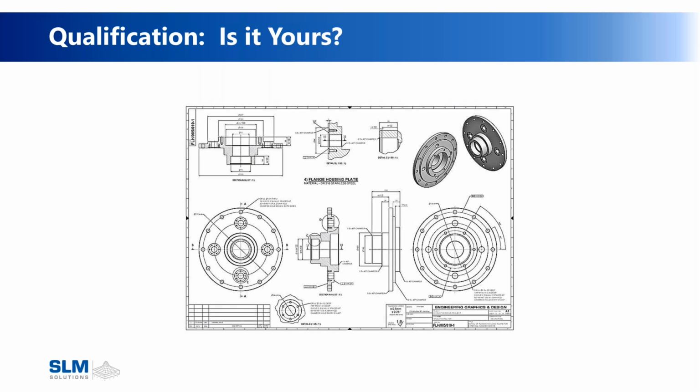Do you own the rights to make it out of powder bed fusion versus a traditionally manufactured part? Is that what is available? A lot of engineering designs call for specifically what you can use to make the part. And if you can go to additive, what type of requalification processes are needed? What kind of costs are incurred by going to an additively manufactured process versus a traditionally manufactured process?